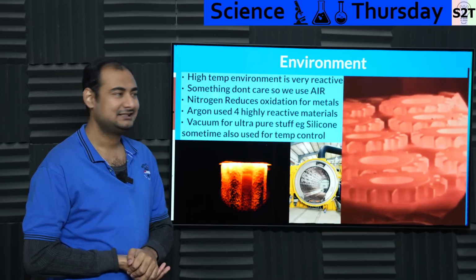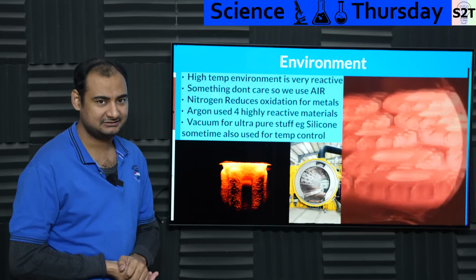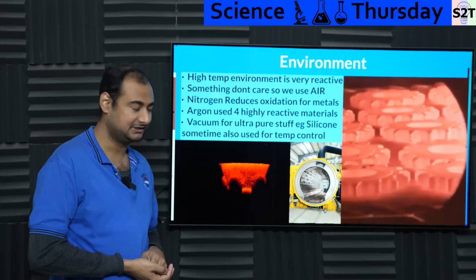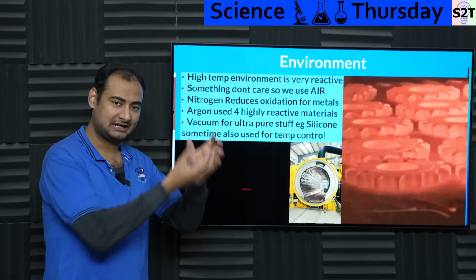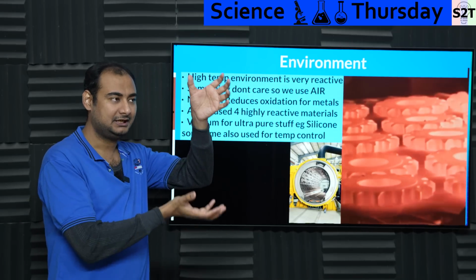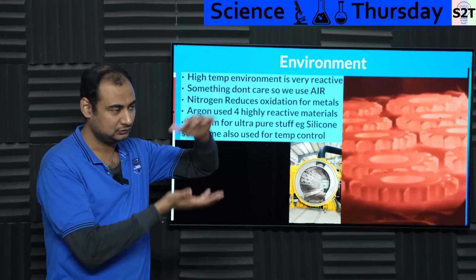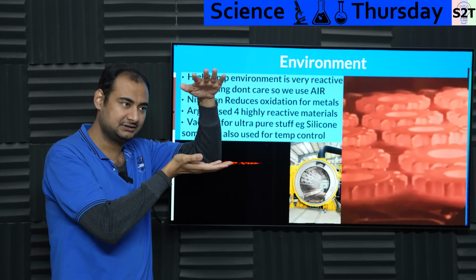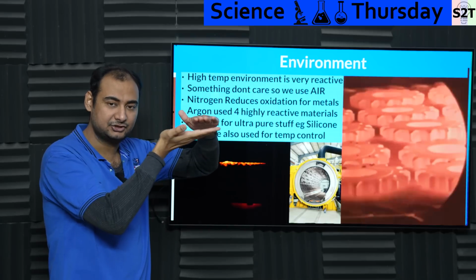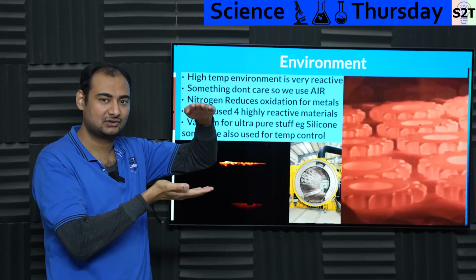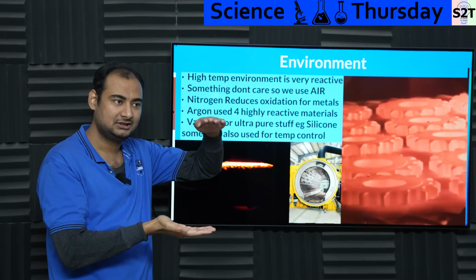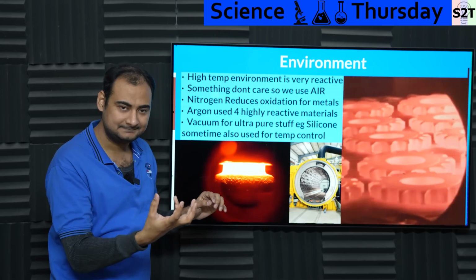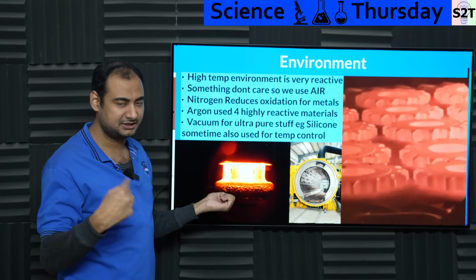Like, wait, what? Well, the most advanced, complicated black magic technology is single crystal turbine blades. Now, how do you make it? Well, you have a molten form, molten metal of super alloys. Cool, awesome. Now you have to pull it down, cool the bottom part, and keep the molten layer line very controlled, as in where that liquid to solidification is happening, that has to be controlled.